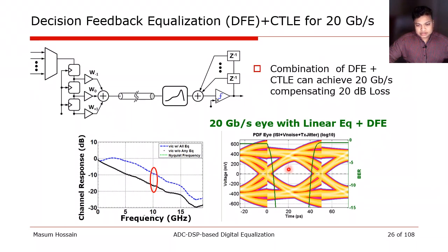Looking at the eye diagram, we notice significant discontinuity. This happens because the input of the summer node is a spread out pulse, whereas what we are correcting after decision are UI wide pulses with sharp edges. Therefore, their summation would show these discontinuities. However, at the middle, where it matters in terms of voltage margin, we see significant improvement.